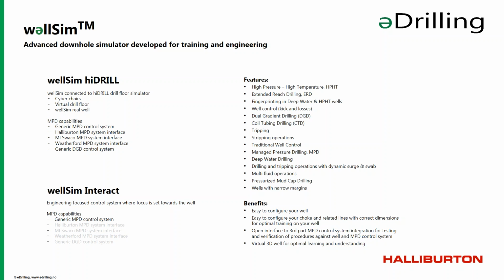The benefits of using this kind of simulator in training, and if you look at the MPD as well, it's very easy to configure your well, the real well that you're actually going to drill offshore. We also configure the real choke with the correct dimensions and the CV curve and so on, so it should respond as on the rig. We also have that open interface to other MPD control systems. And on top of that, we also have the downhole 3D visualization of the well. That was quite quick, but go to the next.